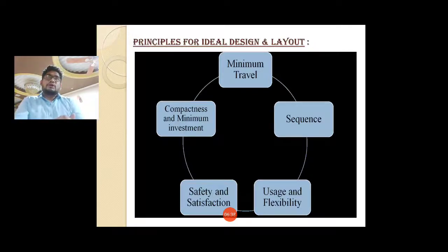In many companies where there is a risk of hazards to an individual, we see that companies like Tata Steel and JSW implement mandatory measures. For example, if there is a risk of hand injury in a particular department or machinery, the machine will start only if both hands are out of the machine, and we need to press two buttons with two different hands, and only then will the machine start.